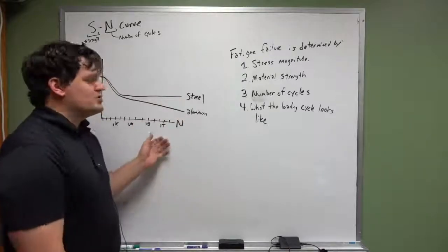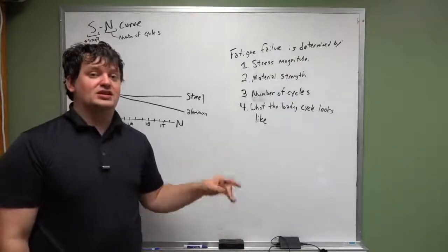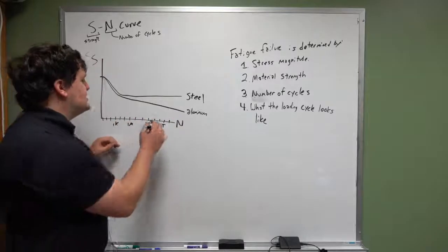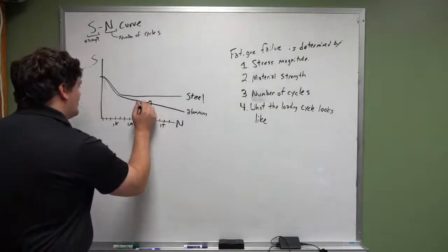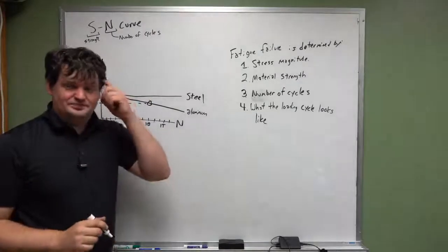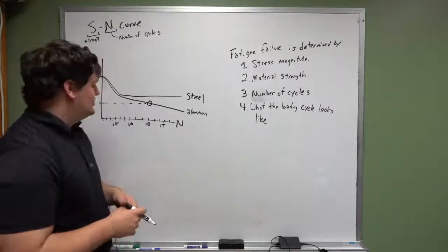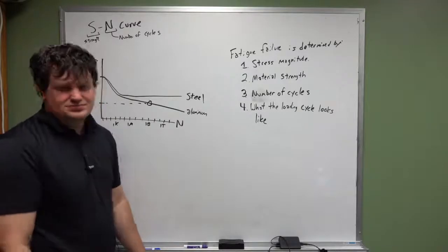So when we talked about materials at the beginning of class and I said steel is better at handling fatigue, this is why. Because with aluminum, if you design for it to have 1 billion cycles, you can figure out what this value is and you can say, that's my strength. But other than that, if you want to go 1,000,001 cycles, it fails.